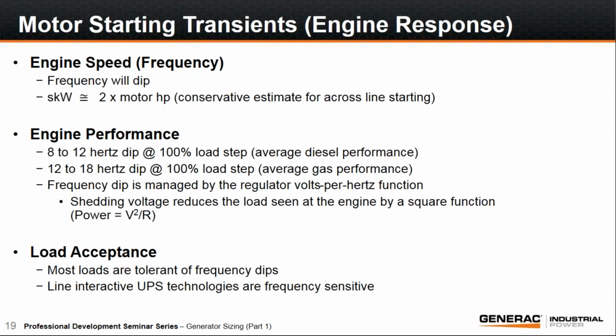How much frequency dip we're going to get changes a little bit depending on whether it's a diesel or gas engine and some of the technologies involved. Most loads don't care too much about frequency dips. Most loads are very voltage dip sensitive. What we find is a lot of our more sensitive loads want to limit voltage dips to about 15%, but the limits on frequency dip generally aren't in play. The only exception to that is older UPS technology called line interactive technology.